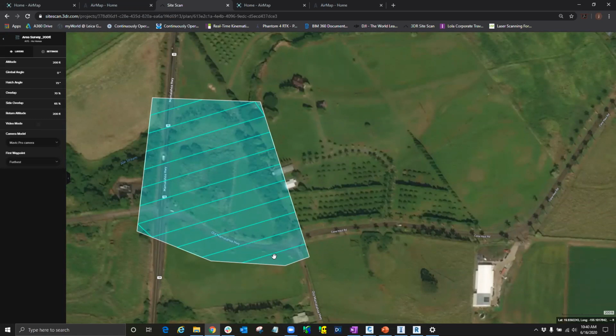I'll give one example with the Phantom 4 RTK unit. It comes with its own monitor, so I can't plug the iPad into it. It's got to be an RTK file, so there's a specific program logged into there. But if I hit pause and then go to resume, it's the same sort of thing if you're swapping out batteries, right? If you're doing a really long flight, you may run out of batteries, so you'll pause, land it, swap out batteries, and then go back to executing and hit resume flight.